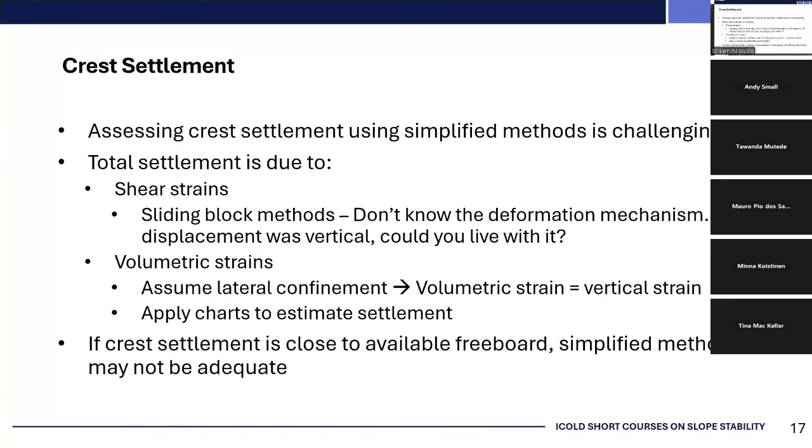But if you have a tailings dam, centerline or downstream construction, or even it can't be upstream because liquefaction is a problem. But if you're centerline or downstream construction, very robust, you don't have a lot of internal drainage elements which are deformation sensitive, and you're dealing with 3, 5, or 10 meters of freeboard, then this approach can be just fine.